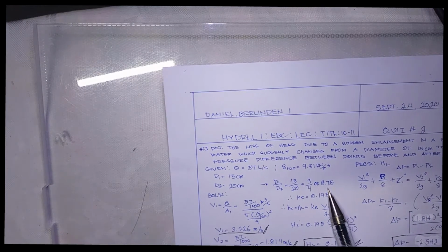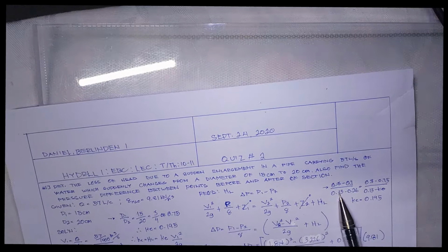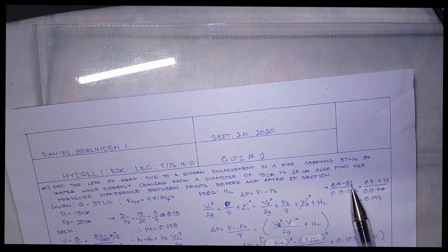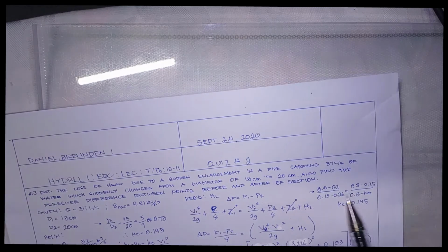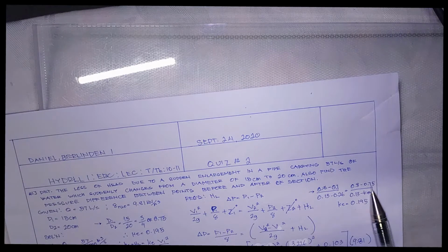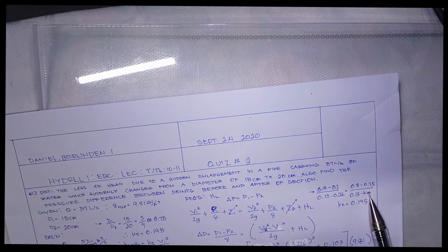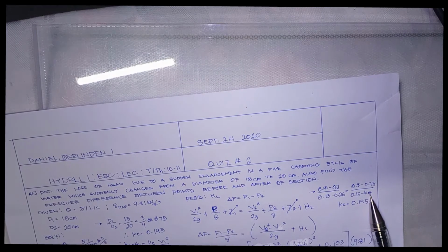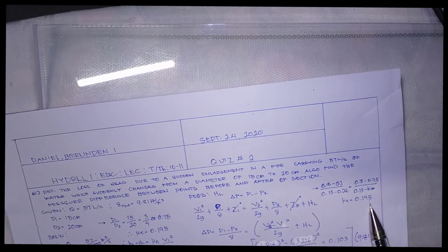And then we will find the value of KE given that value. So we have this given 0.8 minus 0.7, these are given from the table, over 0.13 minus 0.26 is equals to 0.8 minus 0.75, which is the value, over 0.13 minus KE, which is the value of KE given the ratio 0.75. So the value is 0.195.